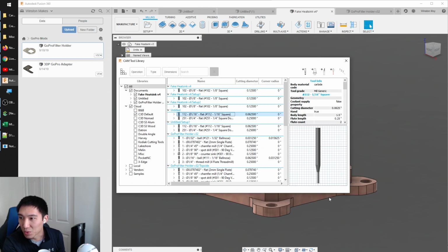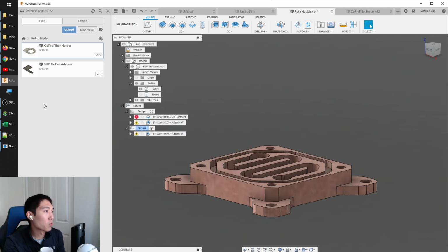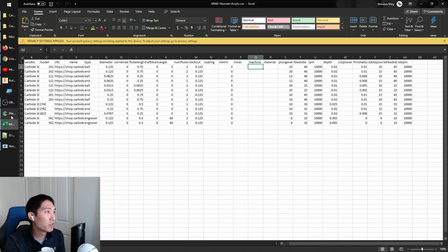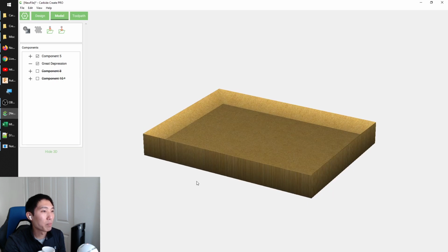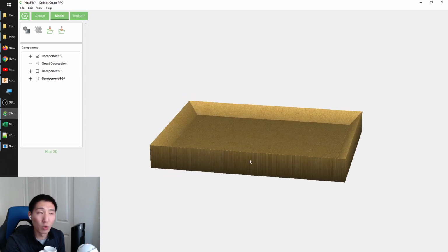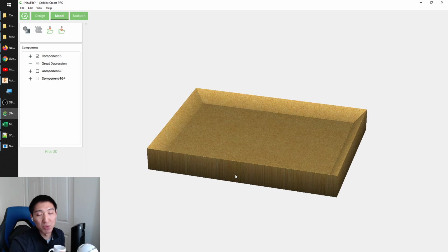Any issues or gotchas you learned when doing inlays? If so, what are they? So right now, when you do a V-carve like this, we don't have a tool for you to automatically calculate the inverse of this so that you can do a matching inlay. This is really just for pocketing. So if you want to carve out large pieces of text, if you want to paint them, this is a great tool.